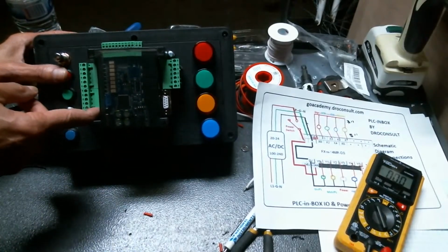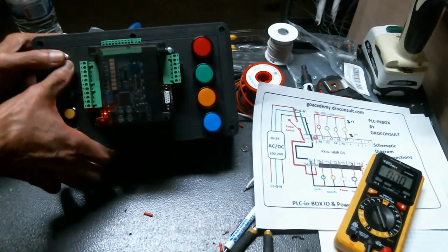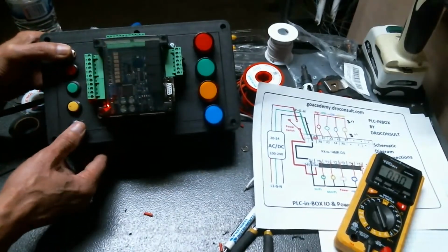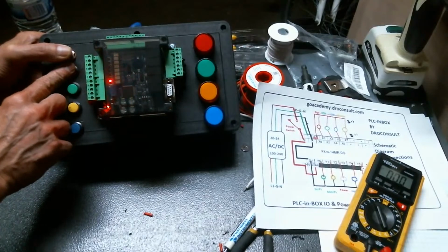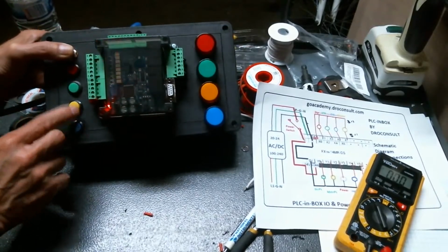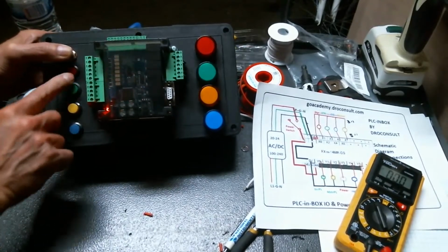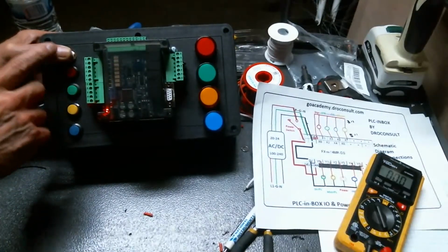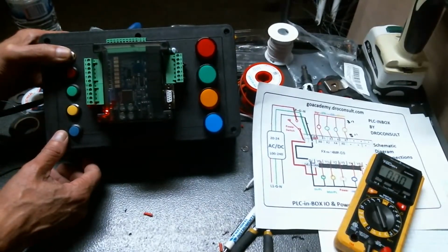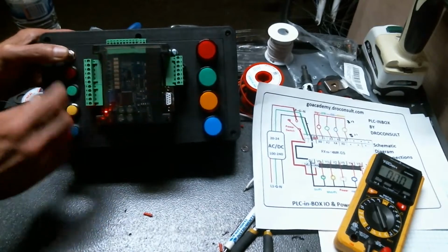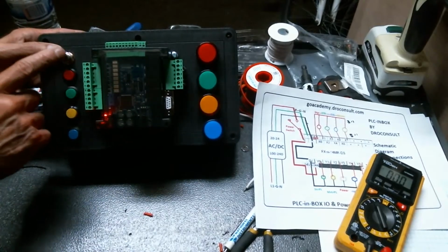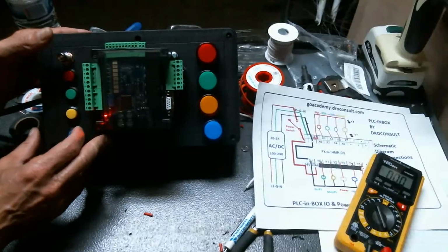There is no program in this controller, and that's the reason why we may not see a lot of action happening here, right? But you can see that the inputs are all working, and they're doing their part. What is not holding is the power switch. So I'm gonna have to replace the power switch. This might be a bad power switch.